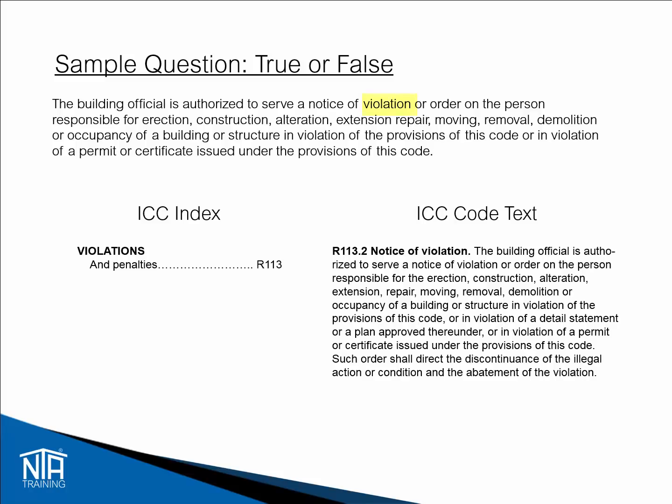This question is discussing violations of the provisions of the code. Look for violation in the index, which will direct you to section R113 of the IRC. Additional keywords such as notice of violation will help you narrow down the possible subsection. Scan the section until you find subsection R113.2, Notice of Violation.